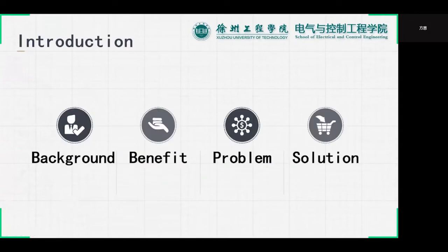As an essential component of modern industry, China also attaches importance to the development of wide bandgap power devices, the advanced manufacturing process of essential core components, and critical basic materials urgently needed by households, appliances, and other industries, which have been popularized and applied. ZVS, zero voltage switching, is realized in LLC resonant soft switching converters on the primary side, and ZCS, zero current switching, on the secondary side. The loss of the converter decreases and the efficiency of the converter is improved.